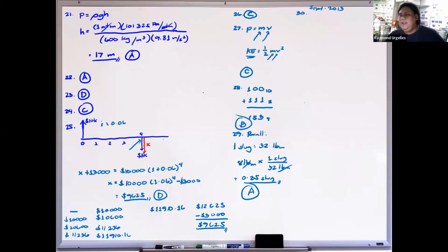Apparently this section in the PEC was removed in 2017, so our reference here is PEC 2009. This is section 2.50.3.7, under grounding electrodes. This is 25 ohms or less.